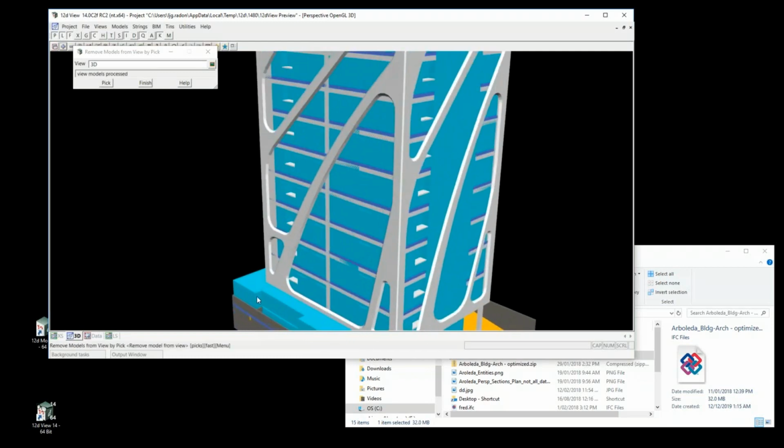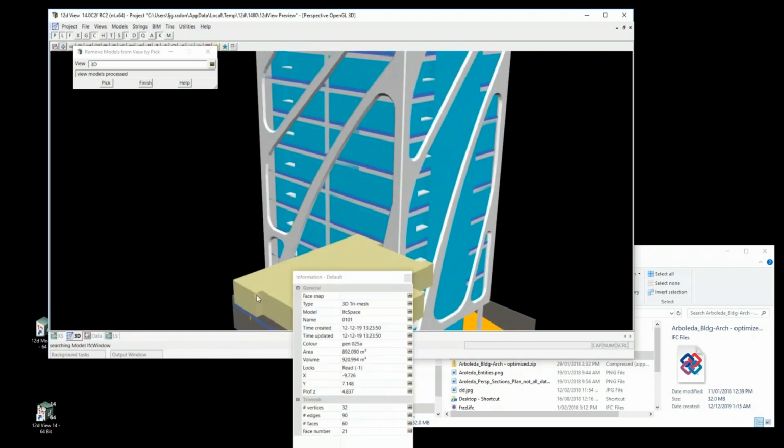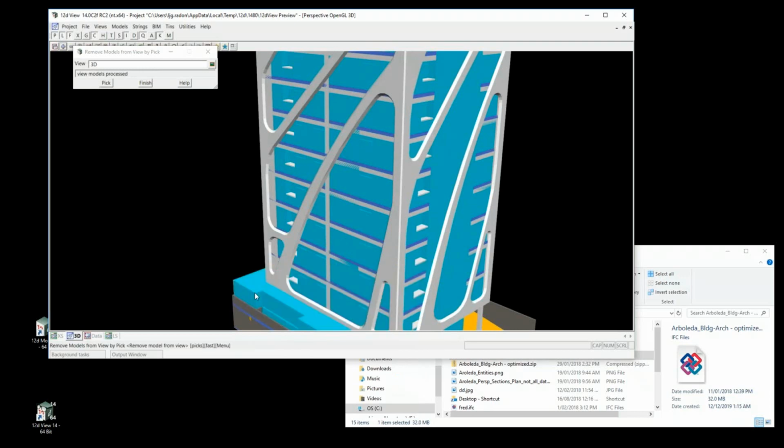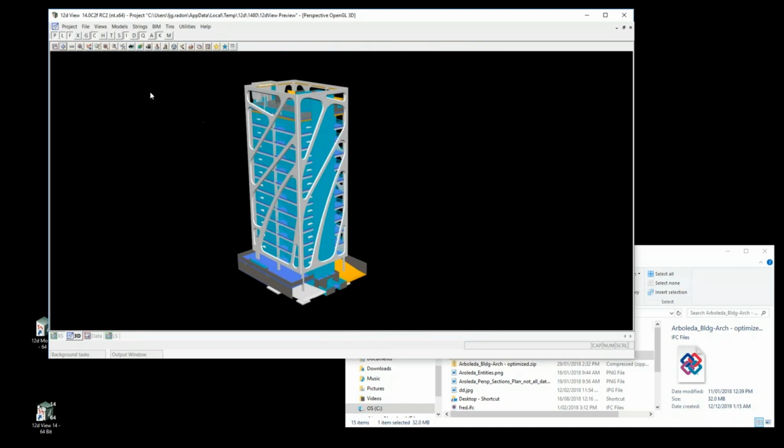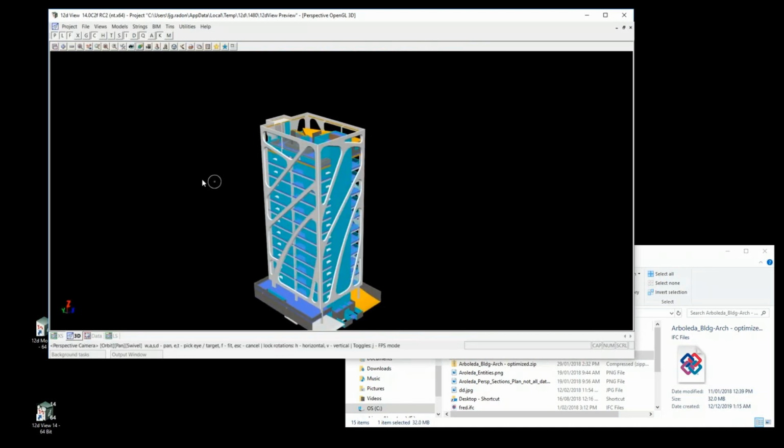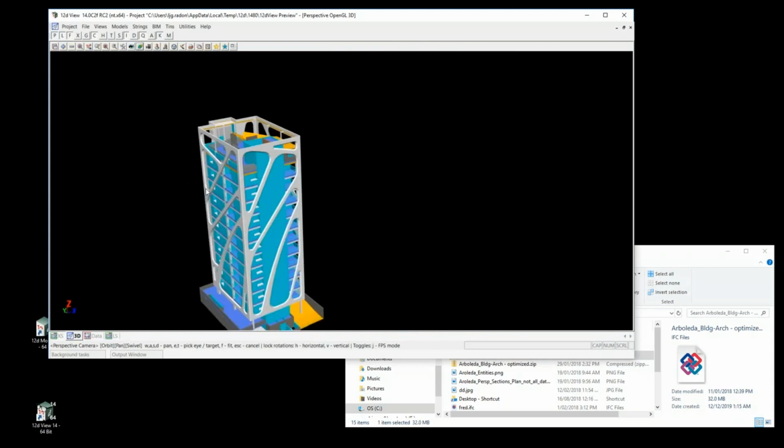And then there's some other funny things down here. Same thing, this is the IFC space, which is just blocks. We often hear about IFC files so you can have volumes of rooms and things like that. Most models just can't generate it like we can with all of our surfaces and things, and that's where this IFC space is. But often you don't want to view it when you're looking at your building. So those sorts of things, properties, just the same as in 12D model. You've got your orbit, other things available, just the same as inside 12D model. So that was an example where you can just drag and drop things on.